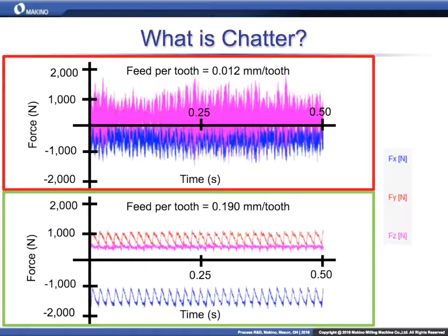And you see erratic and unpredictable and also higher cutting forces than you do when the tool is fed at an appropriate amount. So there's probably some noise and squealing that occurs. It sounds awful. So this is one type of chatter you get.